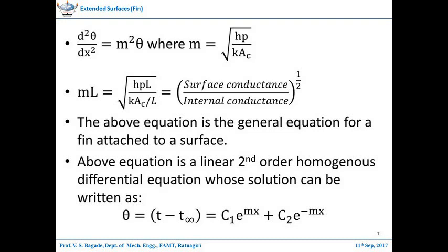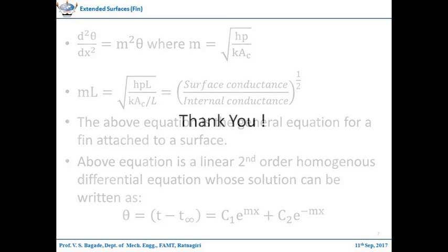The solution of this equation is theta, equal to T minus T infinity, is equal to c1 e raised to power mx plus c2 e raised to power minus mx. Now we can use this equation to find the temperature distributions and the heat transfer for different cases, that is, the insulated fin, infinitely long fin, and heat loss from the fin, which is also called the exact solution.